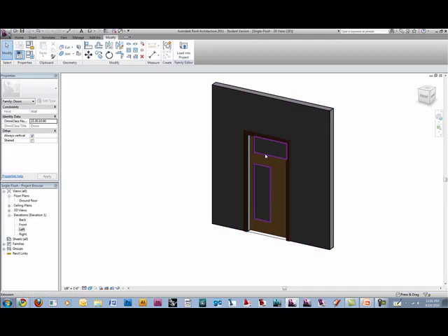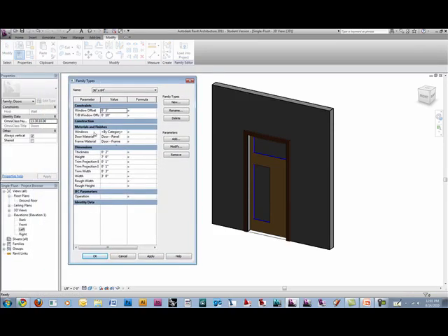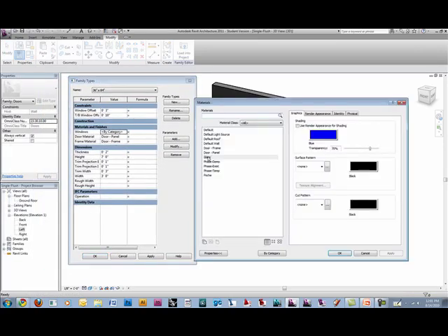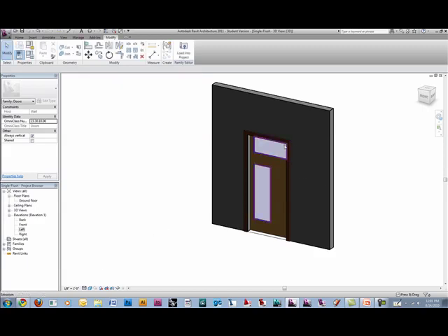Some people think when you add the parameter, it kind of knows what you're doing and does it for you automatically, but it's not true. You still have to go back to the family types. You still have to say Windows. Click that. Make it a material, glass. There's one thing, like these doors are just way too common, but we're going to leave it. You can always change these materials, and I would say change them. Even if you wanted to take off the trim, just take off the trim. You know, that's cool.